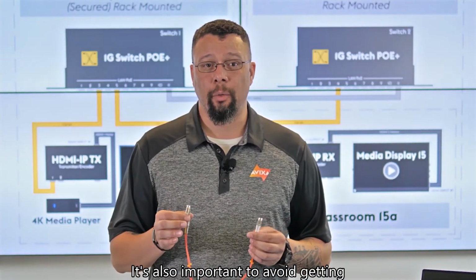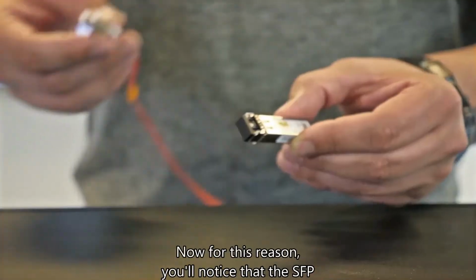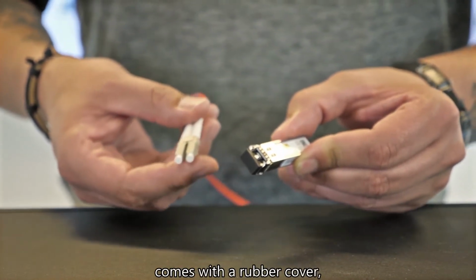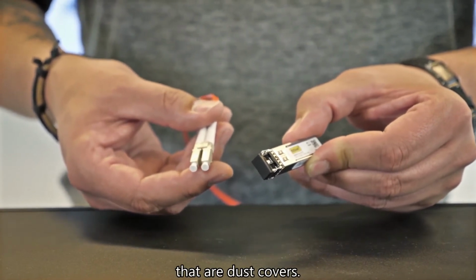It's also important to avoid getting any of the fiber optic or the SFP dirty. For this reason, you'll notice that the SFP comes with a rubber cover and the fiber optic comes with little round caps that are dust covers.